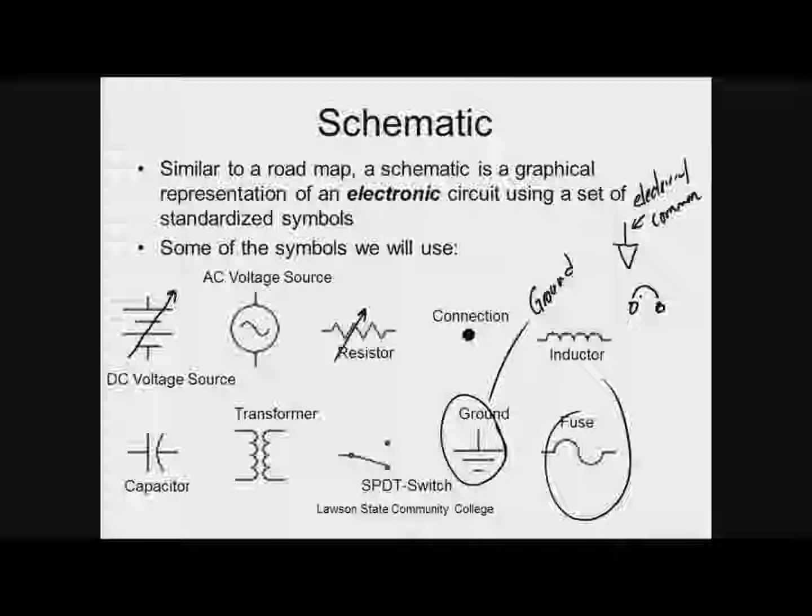These fall into a category called overcurrent protection devices. And they're rated in two things. They're rated in how much current they'll handle through them before they trip or pop or blow. And then the other thing they're rated in is how much voltage they can break. So if you ever look at these overcurrent protection devices, they should have two ratings on them. So you wouldn't take a circuit breaker that's rated for a car that's rated at 14 volts and put it in your house where you've got 120 volts worth of push. Because it could literally do what?